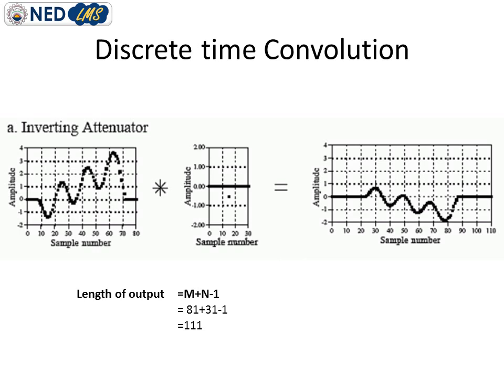In this example, you can see the input signal runs from 0 to 80. It means 81 samples. The 0 sample is also counted because it is a sample, it occurs at n equal to 0 but has some value. So the total number of samples is 81. For the impulse response, samples vary from 0 to 30, so the total is 31.